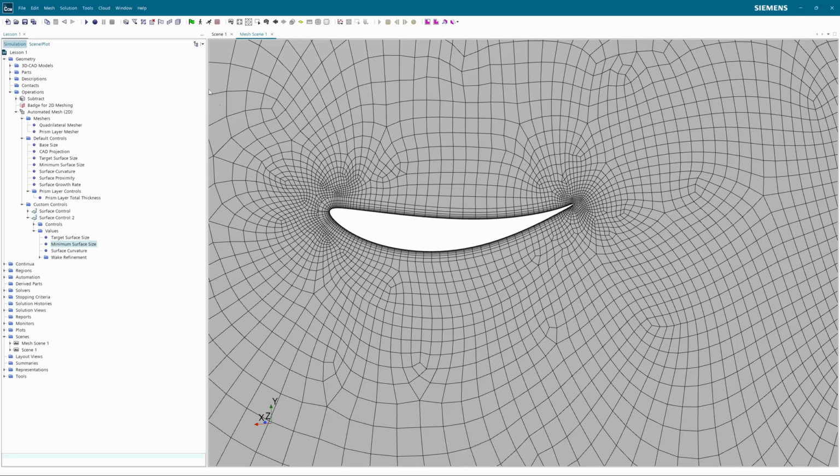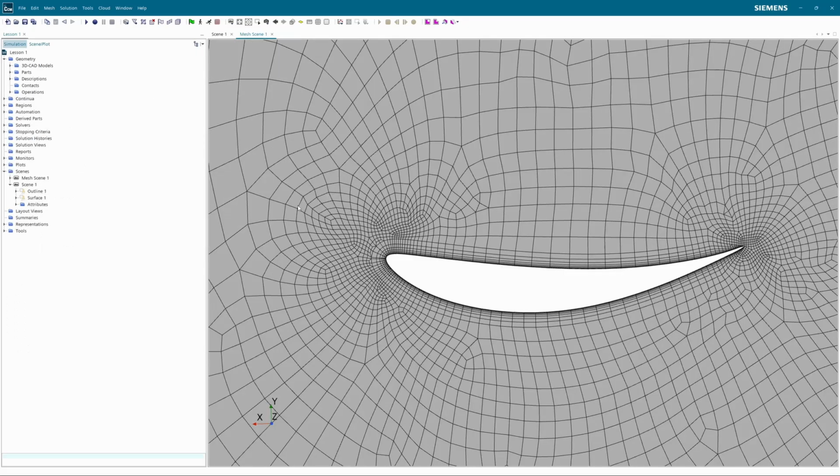For the k omega turbulence model, this value needs to be between 1 and 5 to be correct. It can be lower. There is no problem in that. So I will now show you how to visualize this.